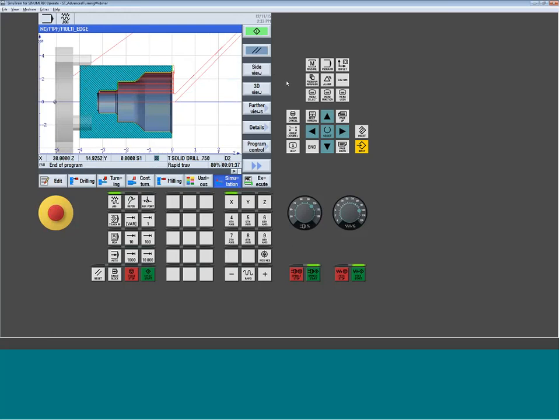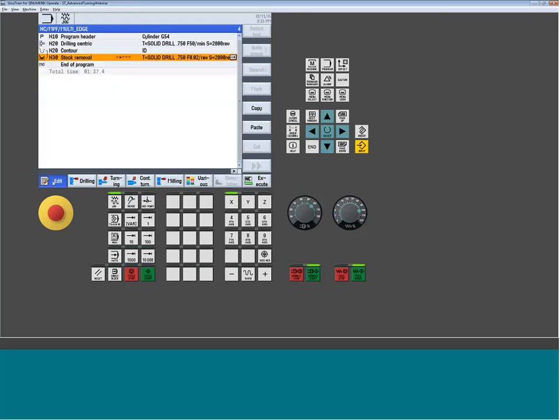And you can start to get pretty creative with those cutting edges. A lot of times I'll use them with grooving tools where I want to hold maybe an offset from either the leading edge or the back edge. So I might create, you know, 2 or 3 different cutting edges for grooving tools.